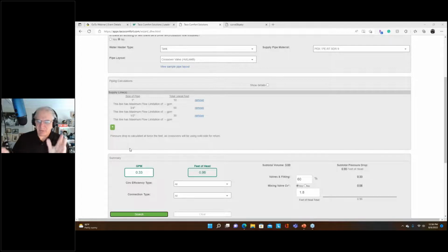When you have a timer, when you have time on your side, the size of the pump doesn't really matter in terms of being too small. So we said we might have to go through a couple of cycles with the smart plug to get that hot water line primed. In this case, it doesn't matter. That pump's going to run for 2 hours nonstop. So there's an advantage there. Again, the disadvantage is who sets them up and who goes back and reprograms them in the case of a power outage or a time change.